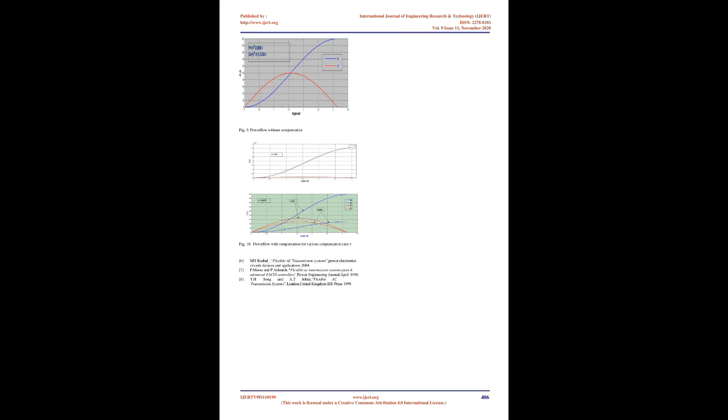The TSSC subsystem is represented in figure 5, and its simulation parameters are given below. Pulse generator: Ts = 5 s, 50% duty ratio, 2.5 milliseconds delay. The basic objective of the simulation is to demonstrate the effectiveness of the compensation technique that we discussed. A double circuit transmission line with a source and some loads, as specified in the above parameter section, is used to demonstrate the compensation technique.